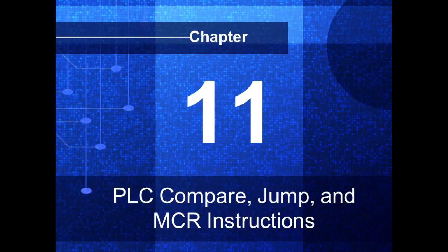And what can we do with PLCs that we can't do with relays? We can compare, and we can jump. And of course we can do a master control reset. We could have a master control relay, which is basically the same thing as a master control reset, if y'all remember that.